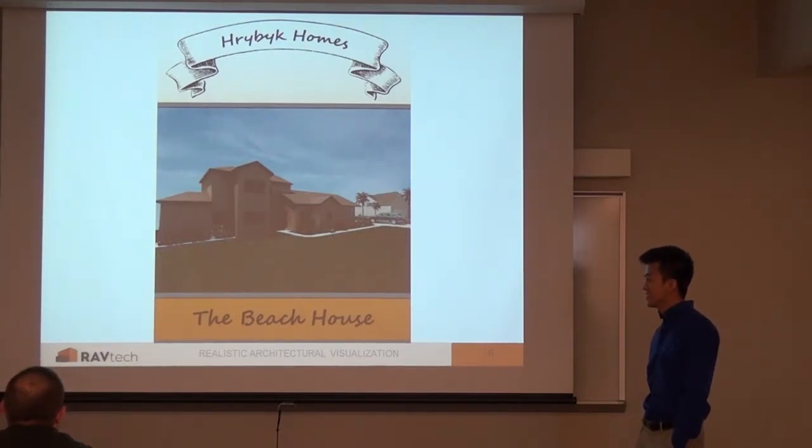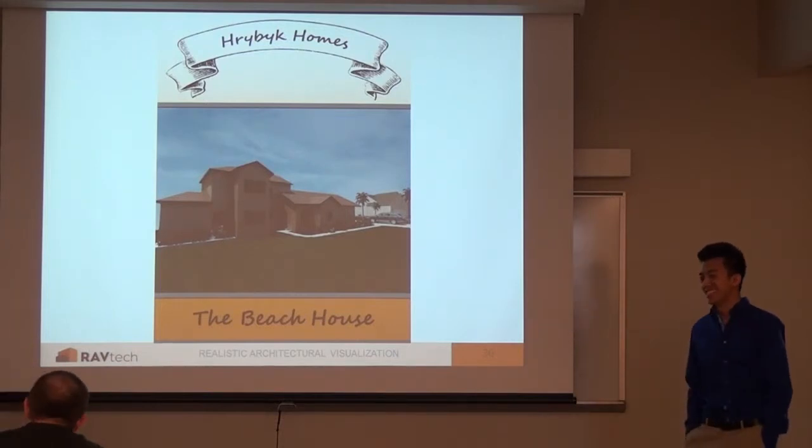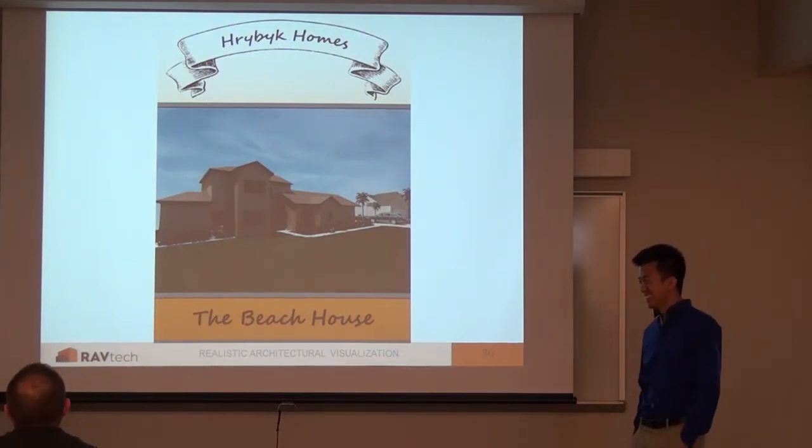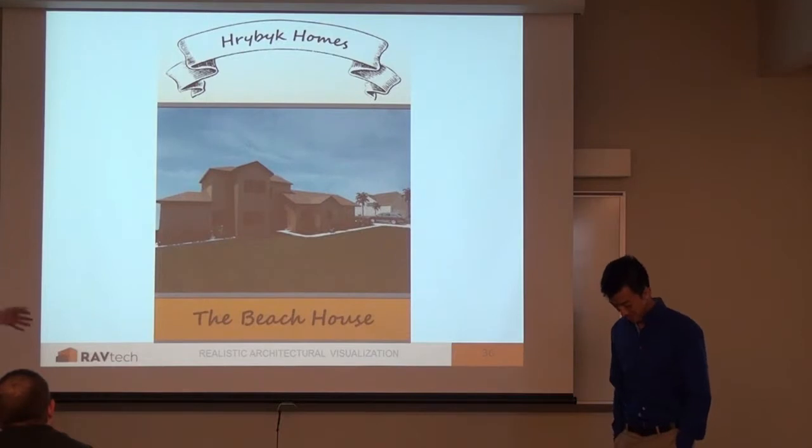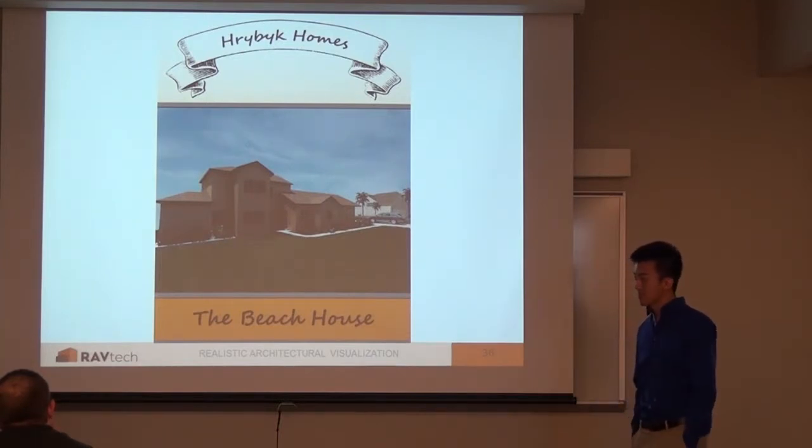Well, funny thing about that one, I created this rendering, and this is something I probably should have mentioned earlier: when you're doing different scenes of the same model, it's a good idea to always start with a new file in Max and re-import it. I ended up doing another scene off of this model inside. I originally had grass modeled in there, and I later took it out and, like Brian did, just photoshopped real grass in there.